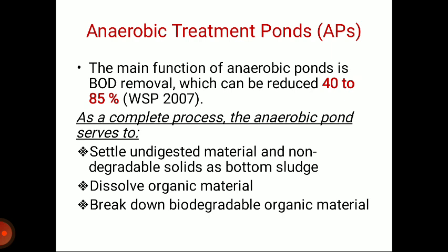The main function of the anaerobic pond is BOD removal, which can be reduced by 40 to 80 percent. As a complete process, the anaerobic pond serves to settle undigested material and non-degradable solids as bottom sludge, dissolve organic material, and break down biodegradable organic material.